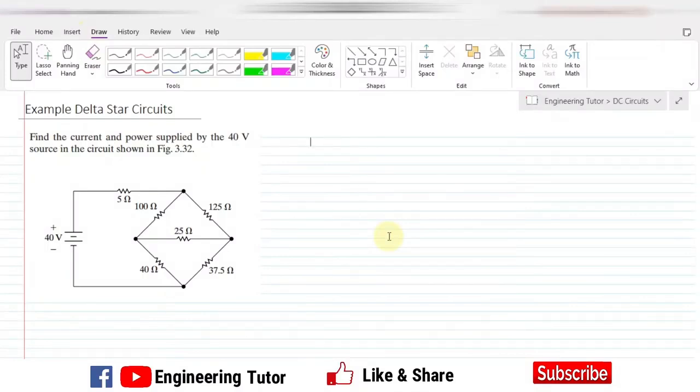Hello students, I hope all of you are fine. This is our lecture on delta star circuits, on how to solve or find the required quantities in a circuit which is neither in series nor in parallel configuration. This is one of the circuits like those, because here you can see that the 100 ohm and 125 ohm resistors are neither in series nor in parallel, because the two ends are neither connected to each other nor in series with each other.